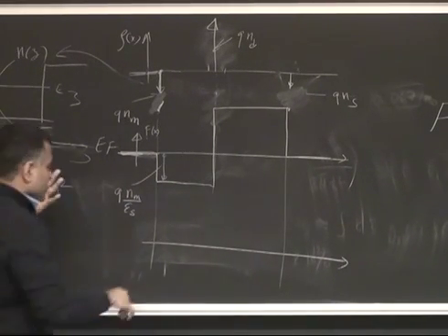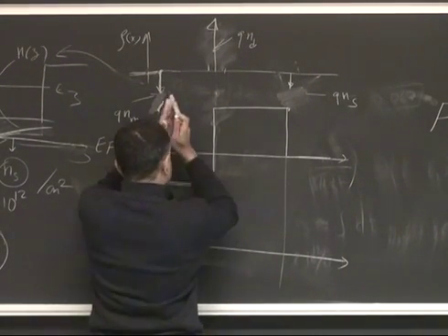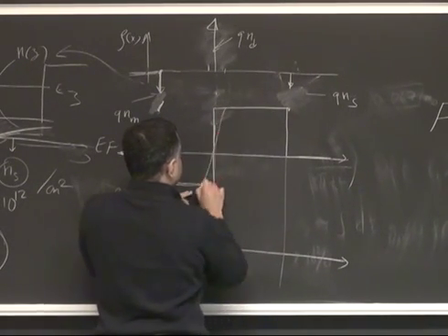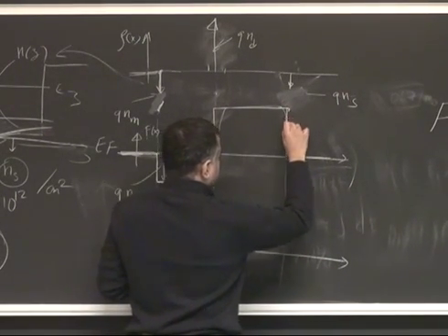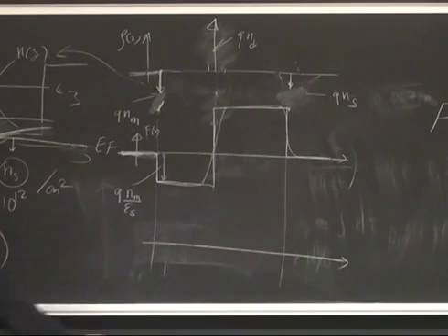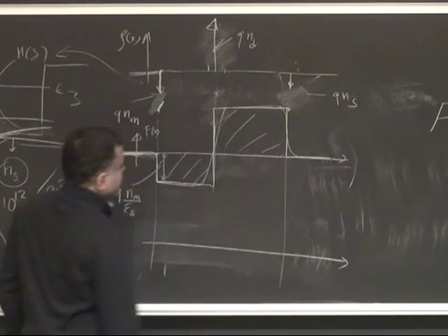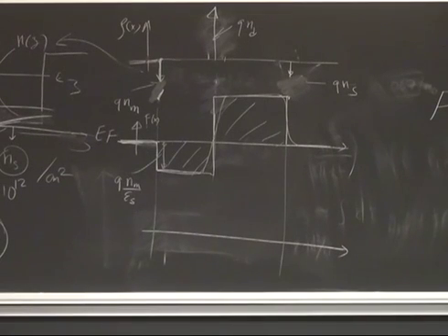In reality, this part remains exactly like it is, but I think you can probably see that if I have a little thickness over which I have doped the region, it will not change abruptly. It will go like that, maybe linearly, right, if it's constant doping. And then you go here, because you have quantum well, band offsets and all that stuff, you will get a little broadening like that. And you can ask your 1D to plot that for you. It will do that, plot the field as well, and this is what you will get. So at 0 bias, when you don't apply any gate voltage and all that, the total area under the curve is what you would call the built-in voltage.